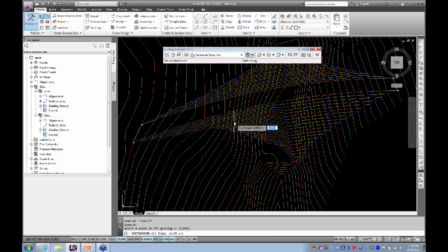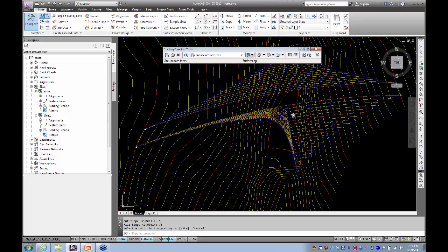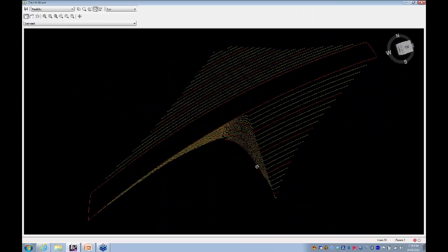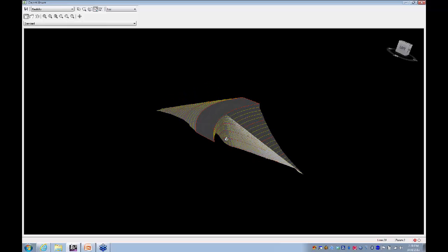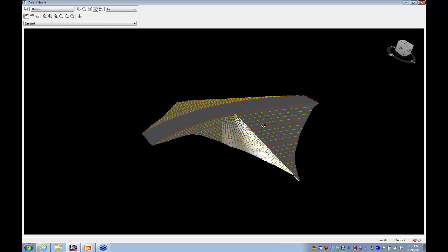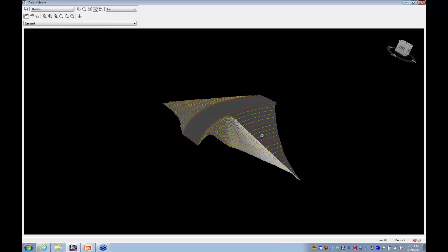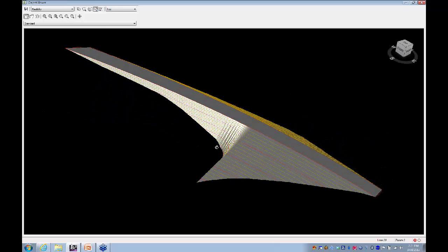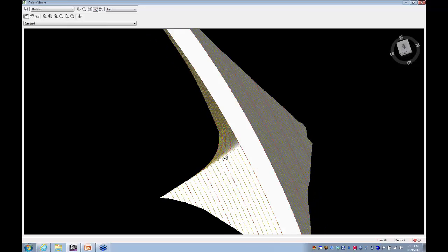So instead of having a 1 and 2 slope on there, let's steepen it right up. Let's go to a 1 and 0.5. And let's steepen that right up. I'm going to hit escape. It'll do that with our surface there, and we'll see perhaps more of a concrete edge of a dam, and then it splays out, and then we can do the rest with earth on that side, perhaps, or realistically that probably wouldn't happen, but at least you can see the ways you can make different shapes happen with these gradings.